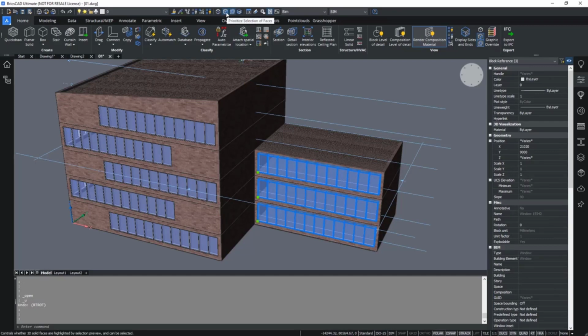For this, maybe make sure that all your prioritizations are off. It will be easier in the next part of the exercise. So in the quick access bar, make sure that none of these icons which tell you prioritize are highlighted.